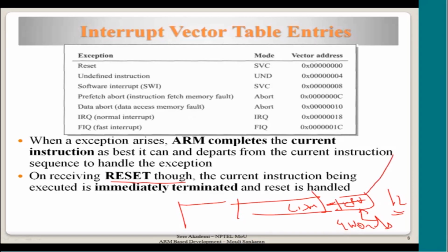The reset signal has come. Okay, somebody has pressed the reset signal. Imagine it could come at any time in the cycle, so it could happen while just 4 words have been transferred. So when the reset signal happens, that is something to tell the processor that enough of what you are doing. Okay, there is a catastrophe. You have to reset the whole system now.